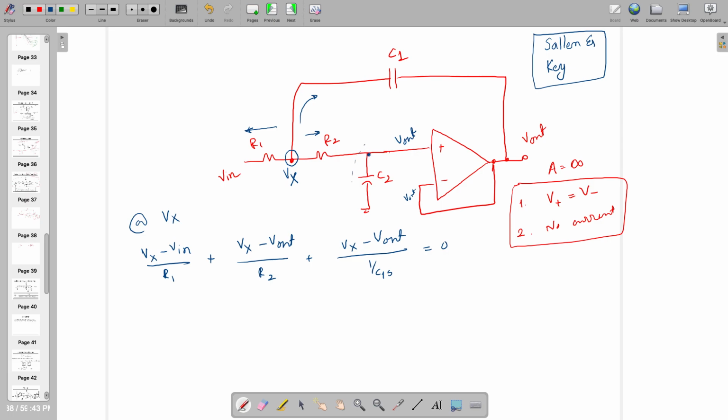what is happening at this point. Look, there is no current flowing inside the op amp, so the current through R1 and C2 will be exactly the same. So can you find out this current now? If both are the same, Vaibhav, are you following? Then what will be the value of the current? Not Vx here.